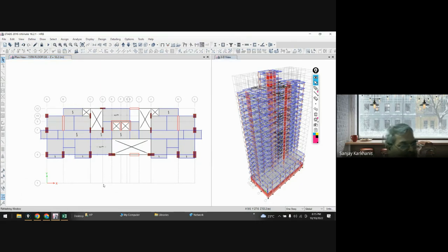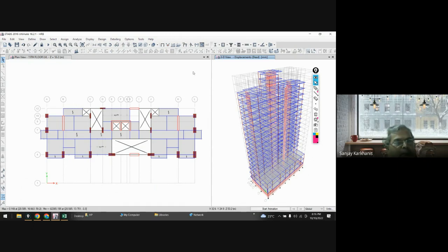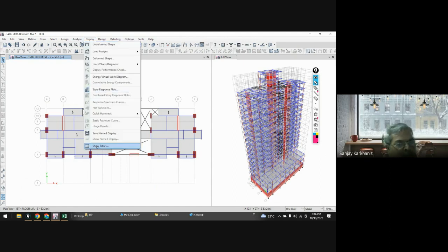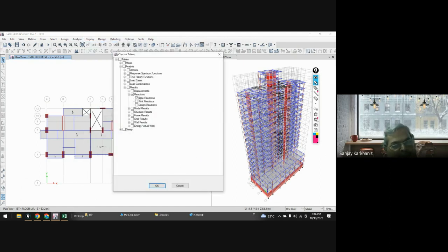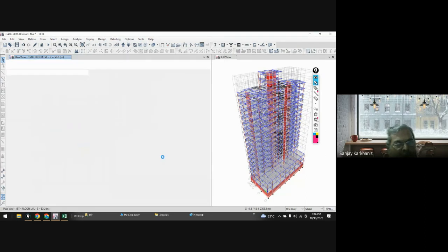Anyway, now you can see everything is the animation, and now you just have to check it. So I'm clicking on this, then going for undeformed positions, then clicking on the left window, going to display, show tables, and under show tables again we'll see that table which we have copied, and you can find the result.